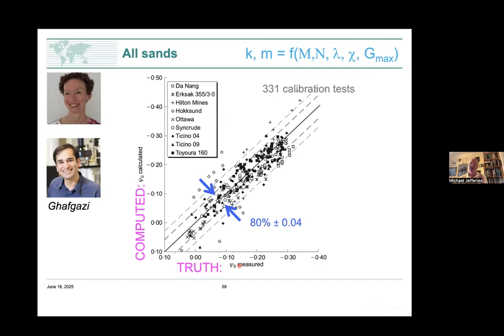We then take their reported Q, stick it into our finite element software, and say I can now calculate, using my computed Ks and Ms, a state parameter. So that's what the state parameter here is. And if our methodology is perfect, everything will lie on a diagonal line with a gradient of 1, which is the line of equivalence. And what we find is, yep, everything does lie on a diagonal line of 1, and there's some scatter, and the scatter is about plus or minus 0.04.